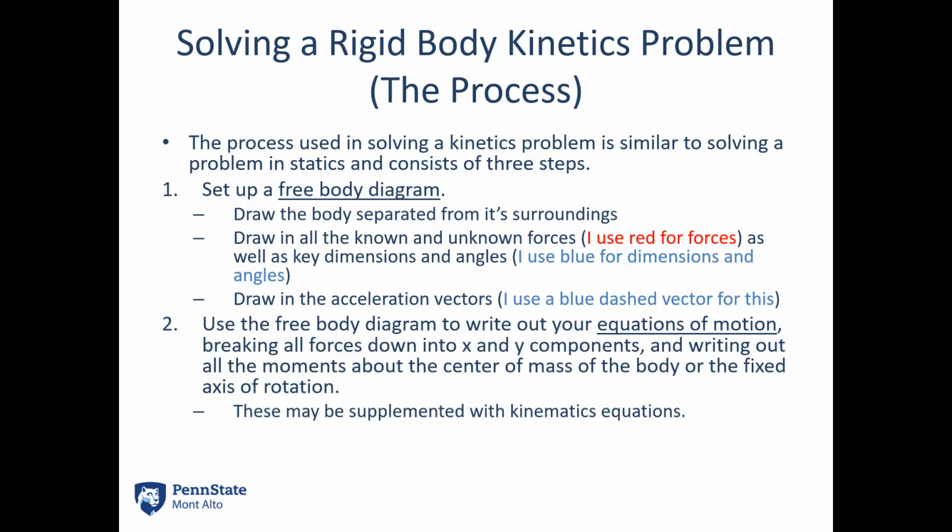Next, you're going to use your free body diagram to write out the equations of motion. So forces and moments, all of this. So break your forces down to x and y, or sorry, r and theta, if you are working with the unbalanced systems. And you can supplement these with kinematics equations. If you've got a way to relate the linear and angular accelerations, you can go ahead and add some equations that way. Once you have all of your equations, you simply solve the equations for any unknowns.